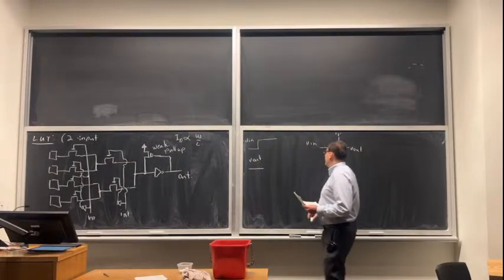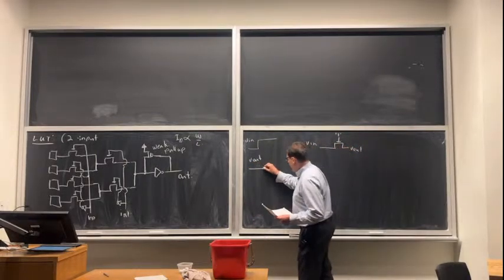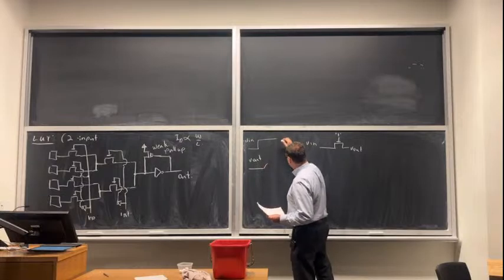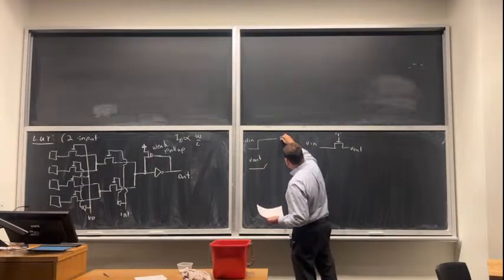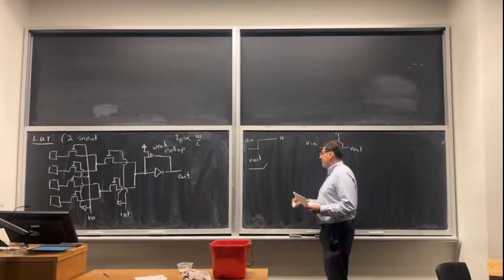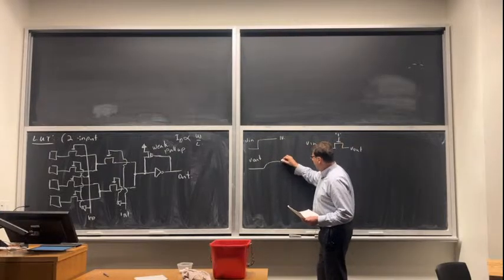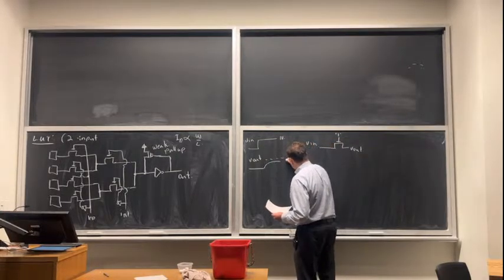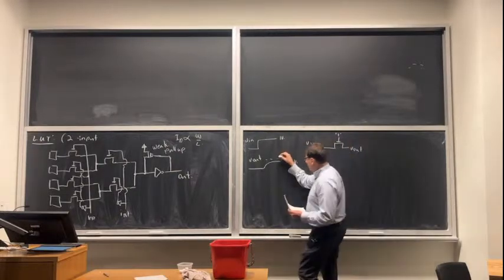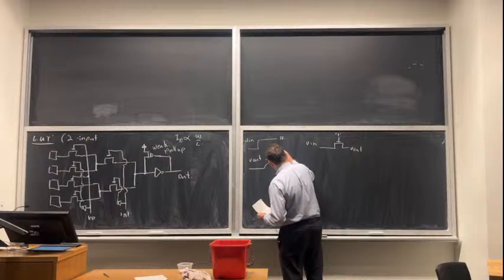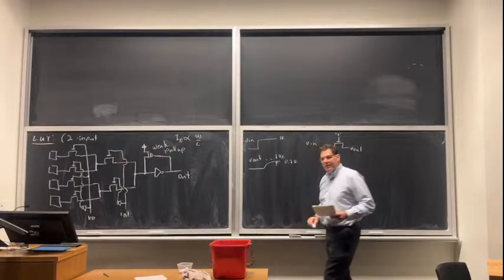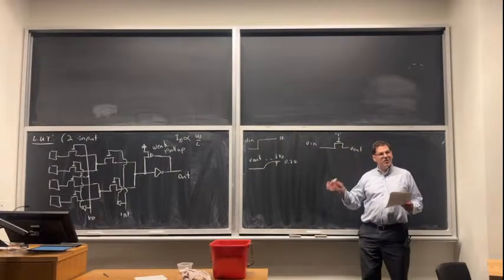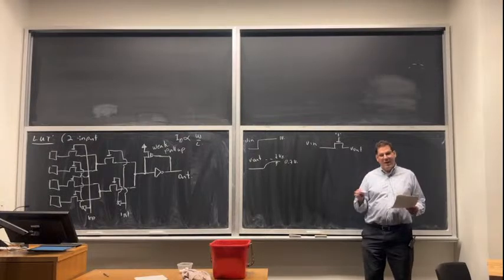When you put the 1 in, obviously there's some delay, so it's going to take a while to climb up. But let's say this is a 1 volt process. This output will not go to 1 volt. It'll go to maybe 0.7. It'll be down by a threshold voltage. Okay, so you have to go back to your transistor level courses from perhaps second or third year.